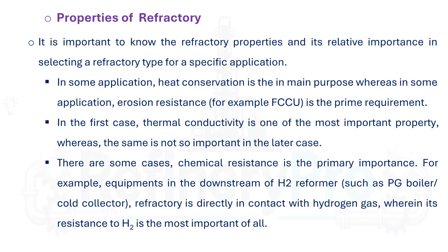Second scenario: consider a fluid catalytic cracking unit, the FCCU. Here, erosion resistance is the prime requirement, because you've got hot catalyst particles racing through at high velocities. Here your focus will be material conservation, not the insulating properties.